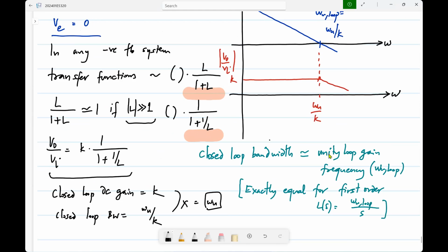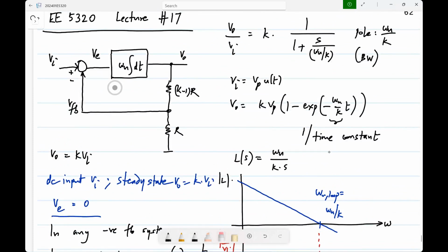So this should also tell you, qualitatively, one of the most important things about these negative feedback systems, right? This comparison is the most important thing. Because finally, the input of the integrator will be driven to 0. Okay. So now, let's say you make some error in this comparison. Instead of Vi minus VFB, you may have Vi minus some scaling factor times VFB. Then that is what will go to 0. Okay, so you'll have some error in the transfer function. Similarly, if some error gets added here because of noise or some other disturbances, then the effect of that also will appear at the output.